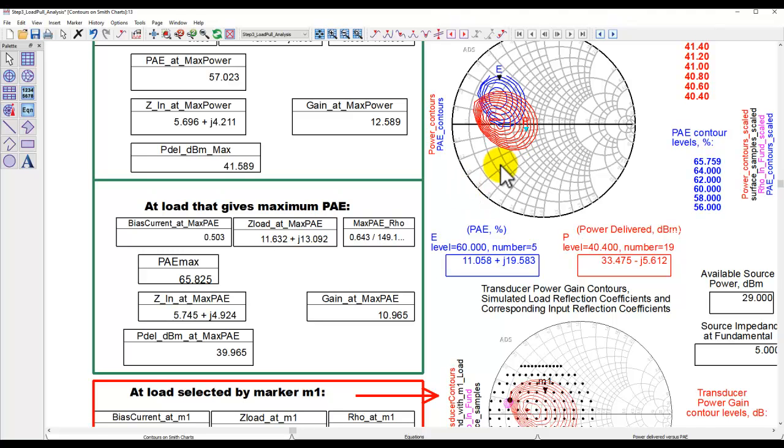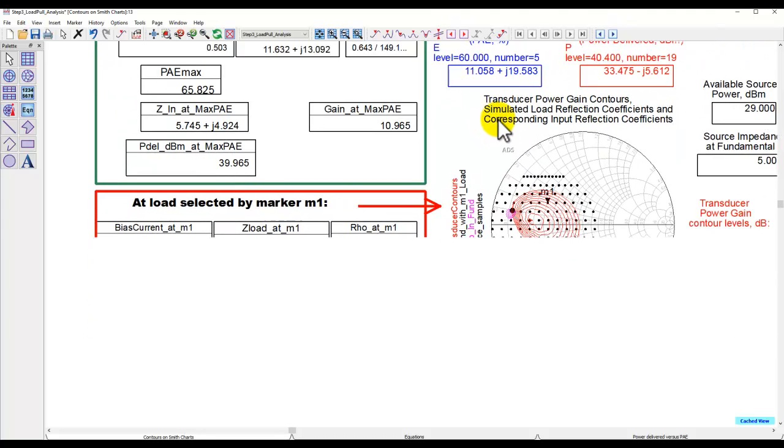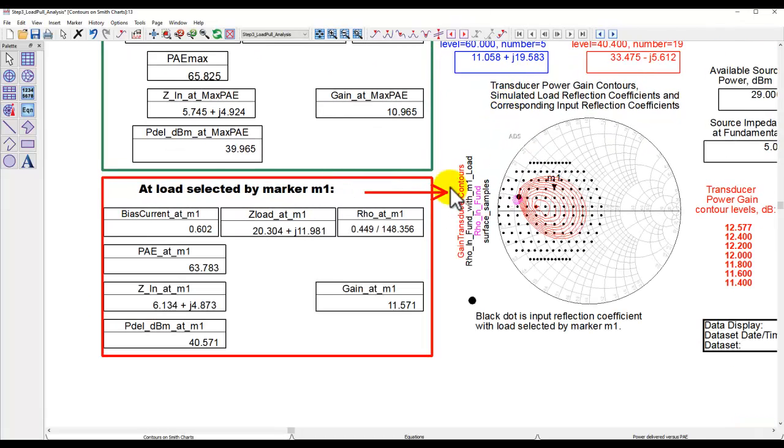You have to have a good compromise between efficiency, output power, and then later, once we start the power amplifier design videos, you will see even the S22, IMD, ACPR, all these things have to be compromised on. And you need to find one unifying point where we can get the best of all worlds to do a proper PA design.